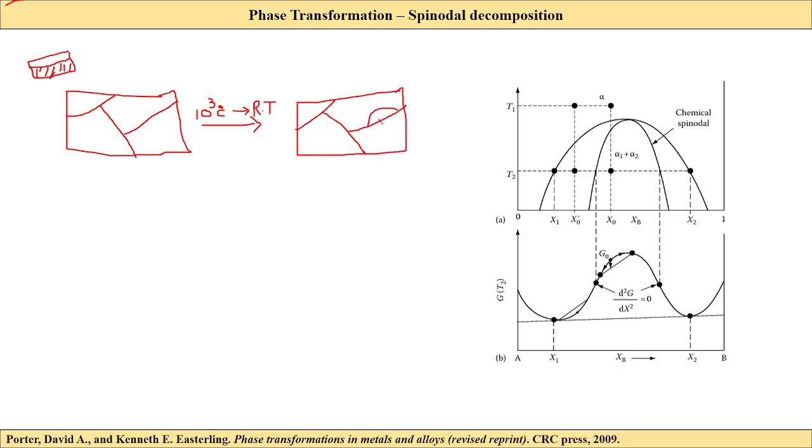Now if something grows on something else, for example on these grain boundaries, or on the mold wall, that is nucleation on a different surface. In homogeneous nucleation we have seen that a new grain will form inside the system, but in heterogeneous nucleation, a new grain will form on a separate entity.